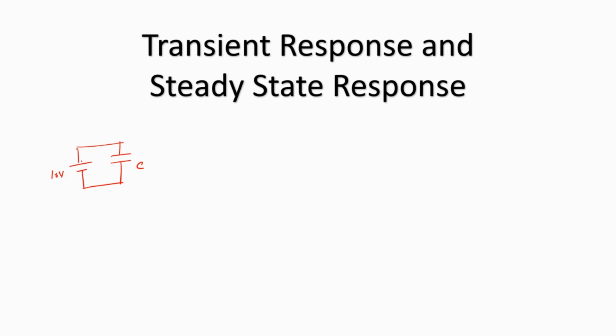Say this is 10 volts. So the capacitor would get charged to say 10 volts. And after some time, I disconnect it from this circuit and connect it to another circuit having just a resistance, say 5 ohms. Now, this change will not be reflected across the resistor instantly.